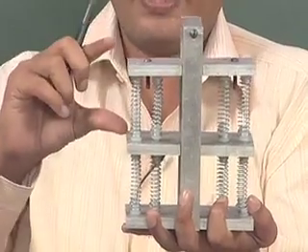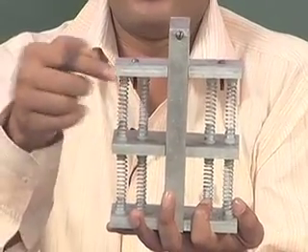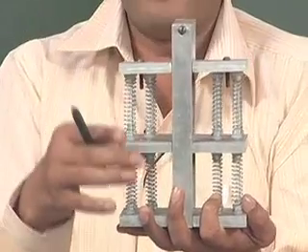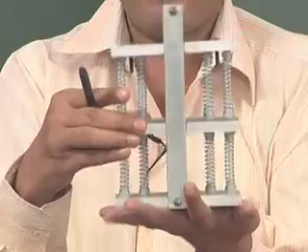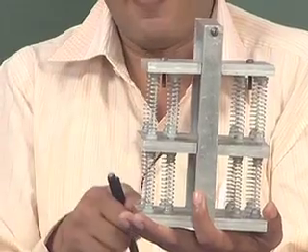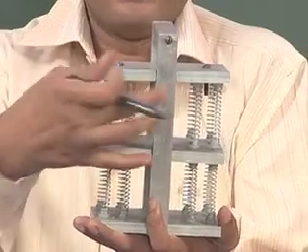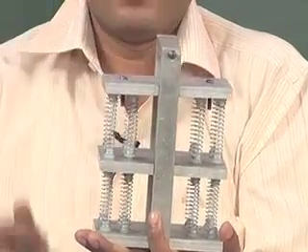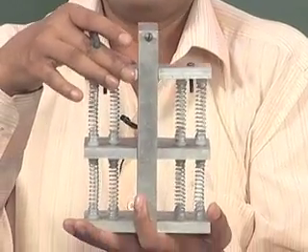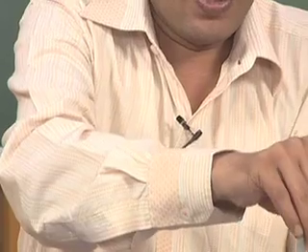So, if you add this secondary system, let this be the primary system, the bottom one is the primary system, and you are adding a secondary system, that is the spring and mass, then the vibration of the primary system can be isolated completely or absorbed completely. So, vibration is absorbed completely when you are choosing the spring and mass in such a way that the excitation frequency of the primary system is equal to the root over of the equivalent stiffness of the spring and this mass. So, root over K2 by M2, if it is equal to omega, then this system can be used as a vibration absorber or tuned vibration absorber. So, those things we have considered before.